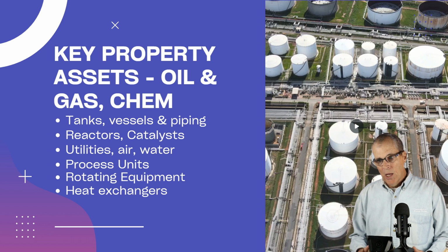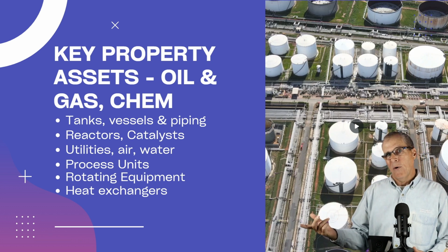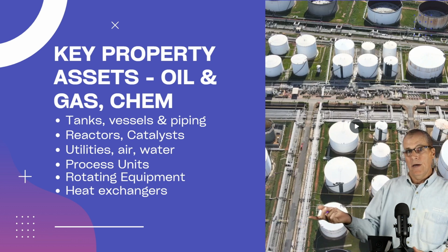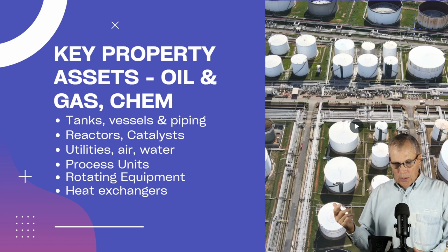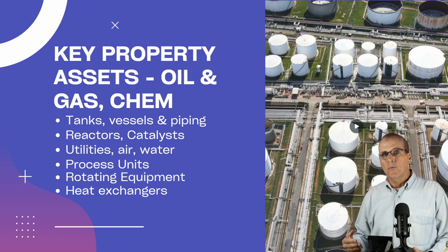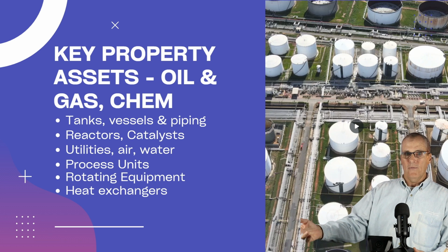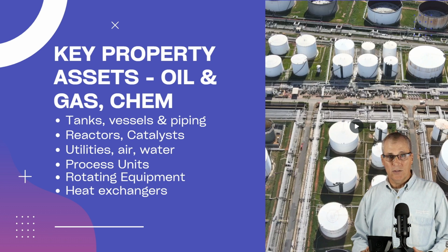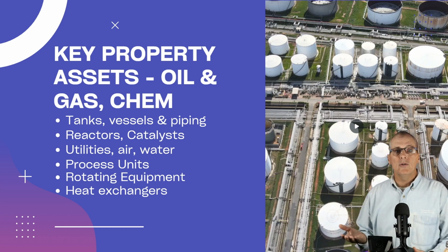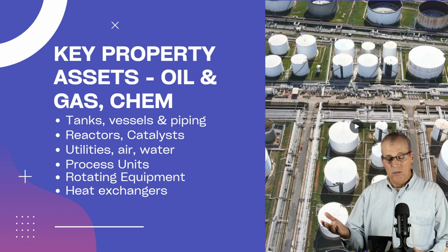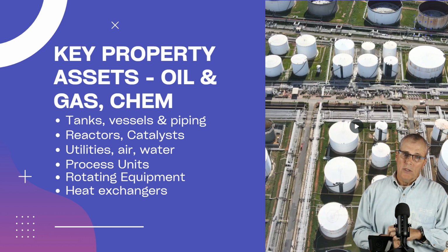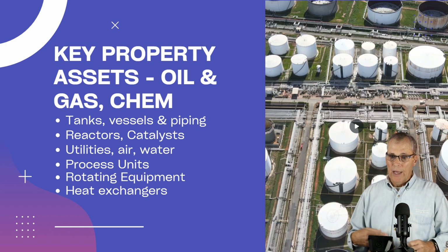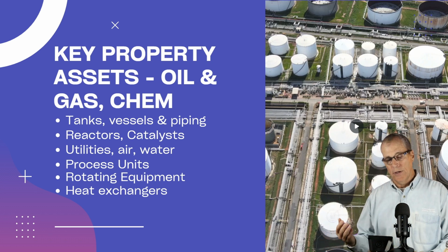And when that happens, the fire protection component may or may not be out of service, depending on how you're connected to it. But definitely you're going to run your fire pump. A 3,000 GPM pump supplying a 5 or 10 gallon per minute cooling system is going to wear out your electric pump way faster than if you were just using it for fire training and fire service. So the water and utilities are crucial to ensure that you have your safety systems back when you need them.